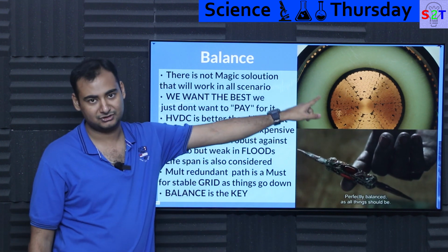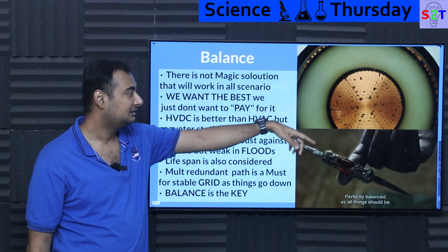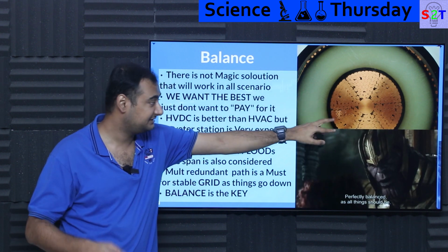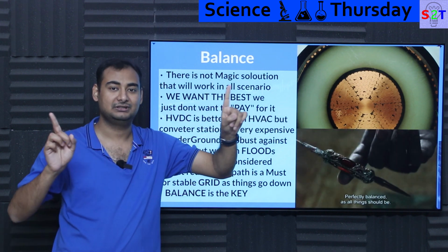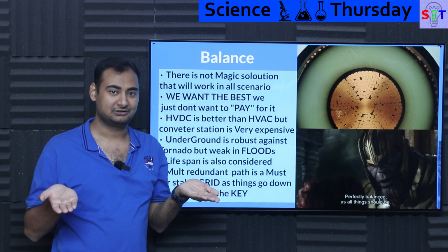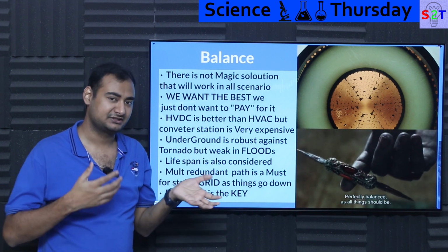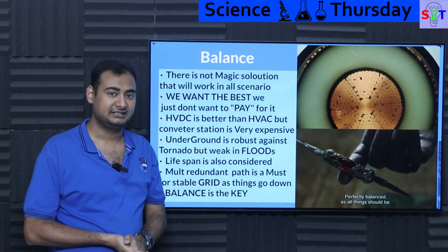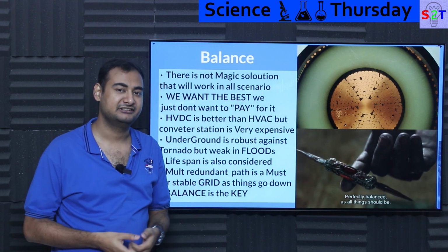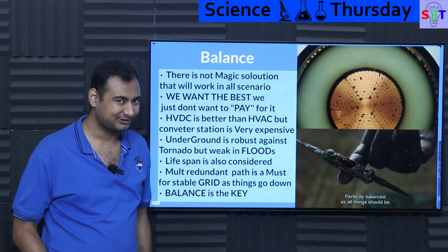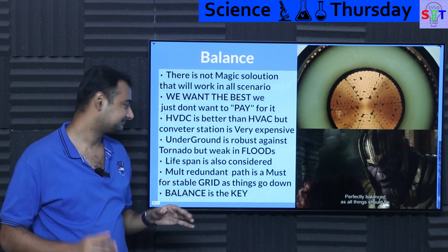These are like a submerged cutaway of a submarine cable, high voltage DC. Again, thankfully, because it's DC, it can utilize the core. Consequently, you see this insulation, this thickness will go YOLO if you increase the voltage. So they have to balance it out. They may be like, hey, what if instead of sending 500, we send 800? This will become longer. Now imagine this cable is, let's say, 150 kilometers long. Would you pay for it? So you have to figure out.